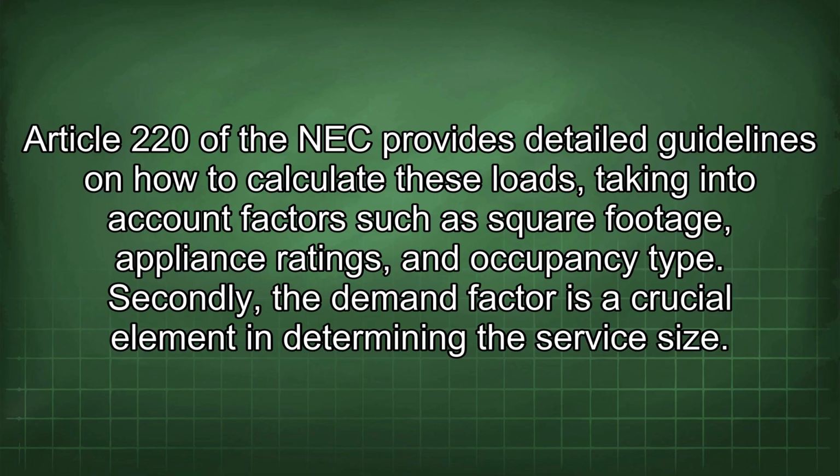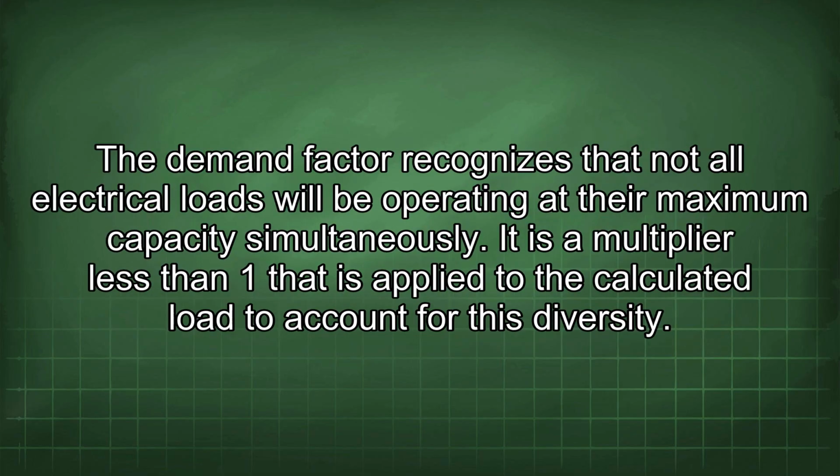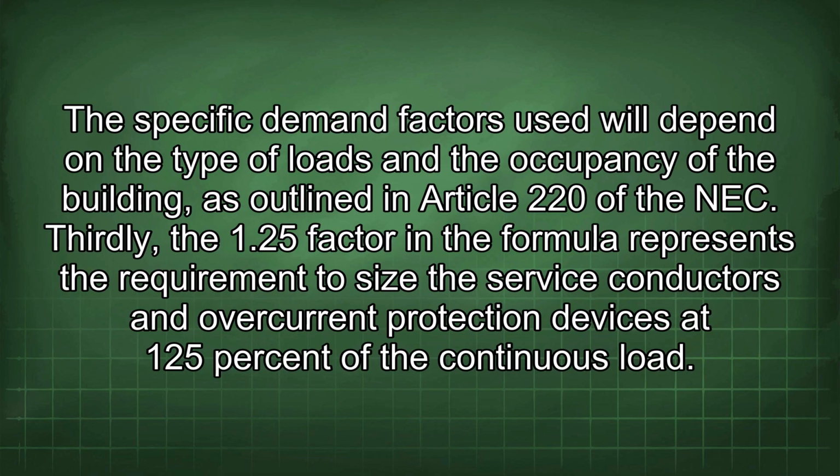Secondly, the demand factor is a crucial element in determining the service size. The demand factor recognizes that not all electrical loads will be operating at their maximum capacity simultaneously. It is a multiplier less than 1 that is applied to the calculated load to account for this diversity. The specific demand factors used will depend on the type of loads and the occupancy of the building, as outlined in Article 220 of the NEC.